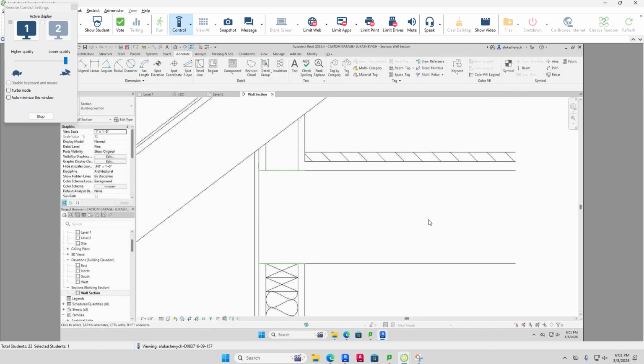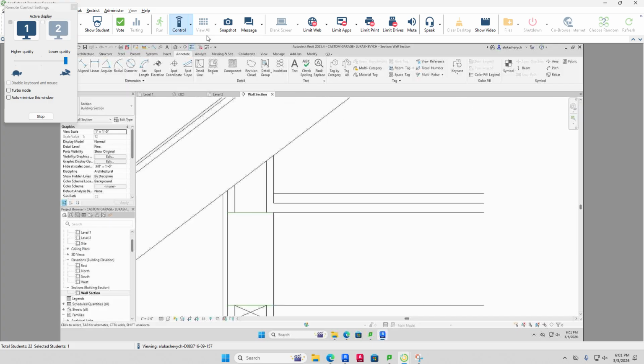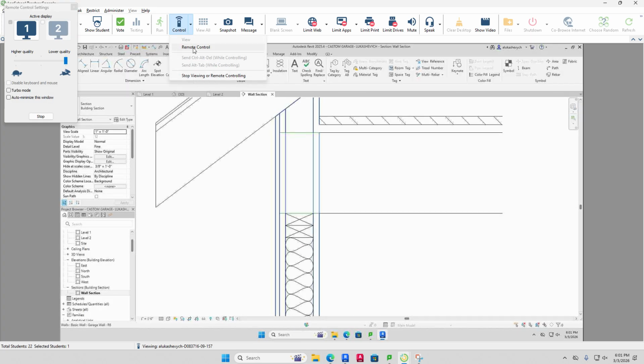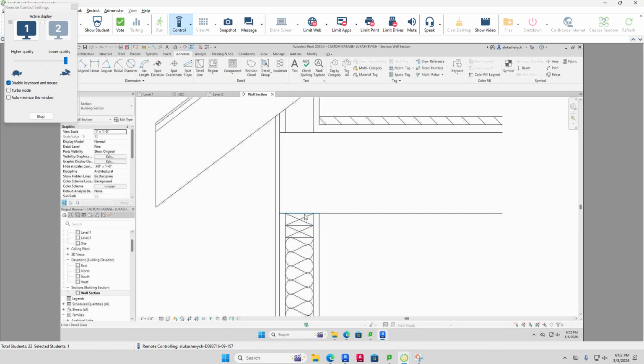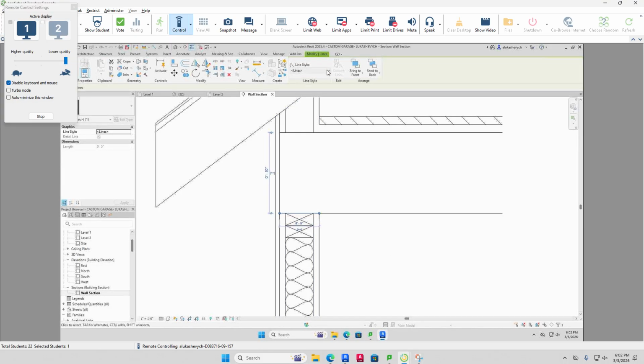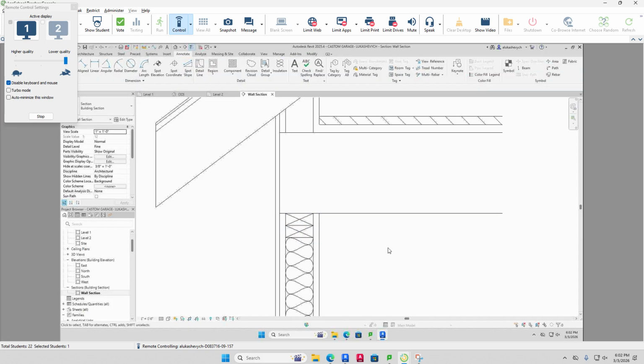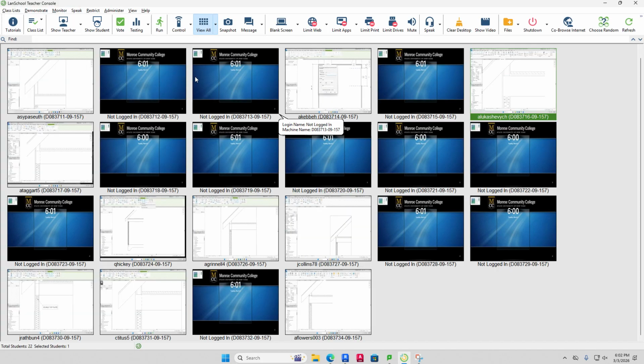Oh, they're green. Yep, I'll show you why. There are different kinds of lines here. If I grab this right here and change it from lines to thin lines, it won't be green anymore. And this one too. So I'll go here and make it thin lines. If you just use lines, they're going to be green because they're a temporary marking type thing. So that's what you have there. Okay, very good.